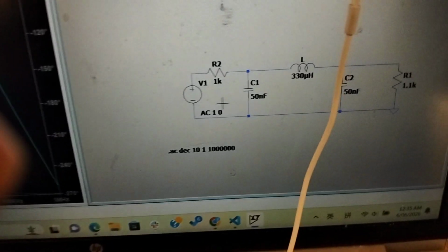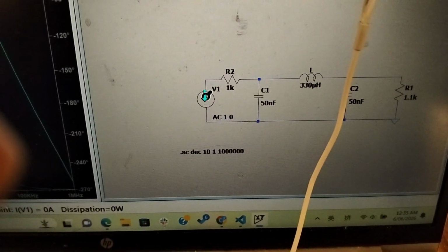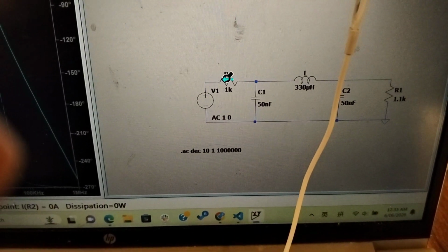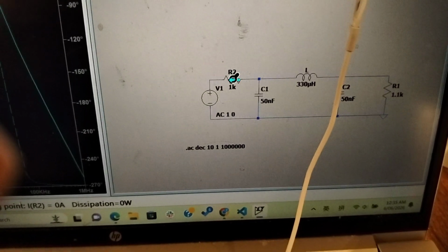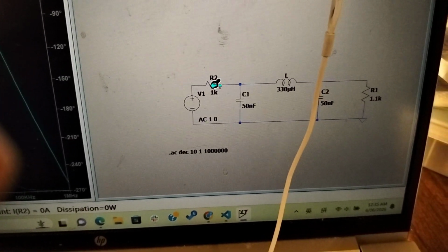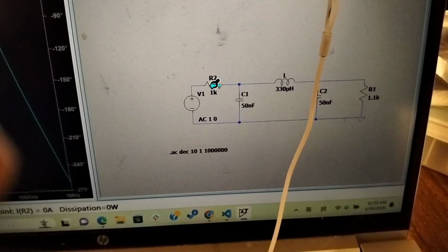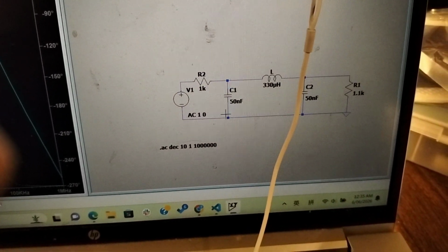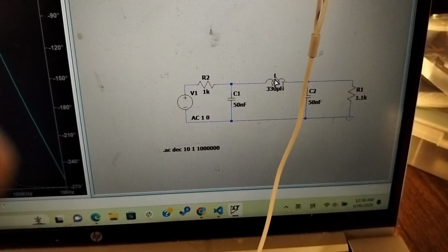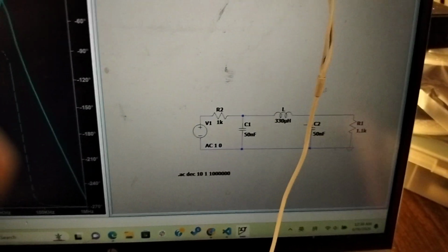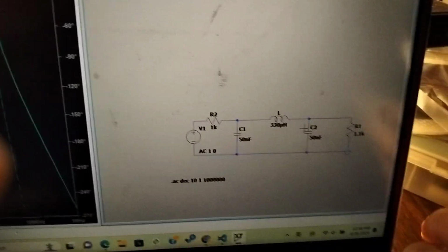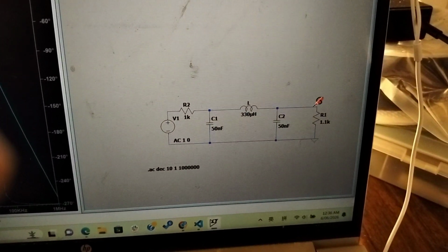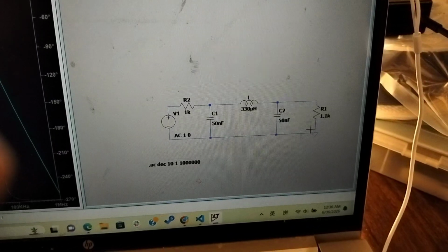It looks like this. So there's some voltage source, and the filter looks like the series resistor, which is the output impedance of the common emitter amplifier. And then there's a capacitor to ground, the inductor and a capacitor to ground, which forms an LC tank. And there's this resistor to ground, which is the input impedance of the amplifier.